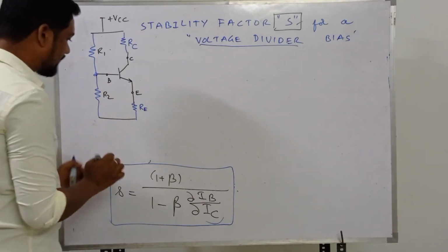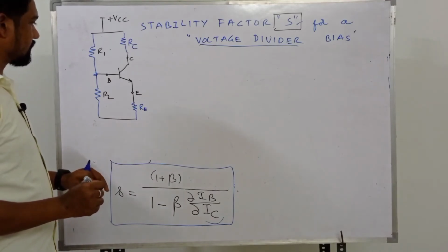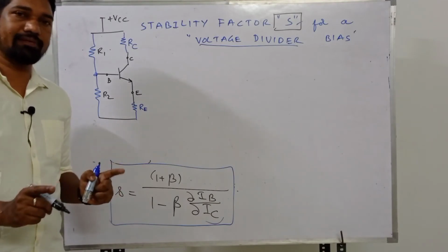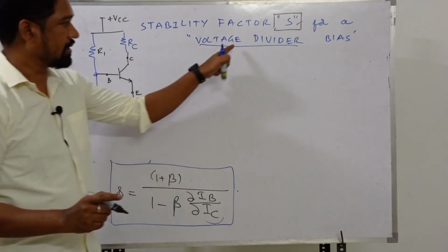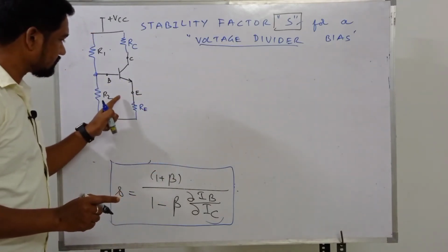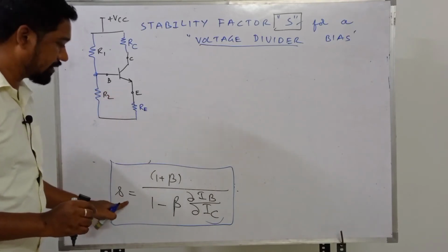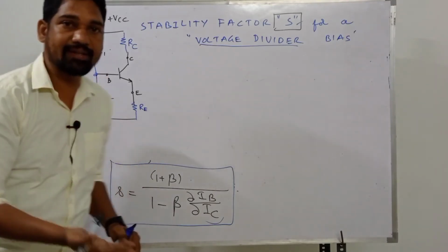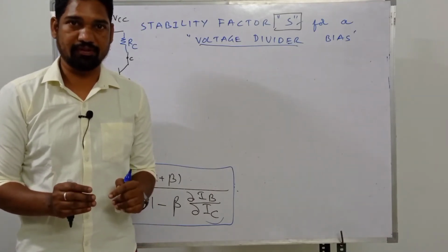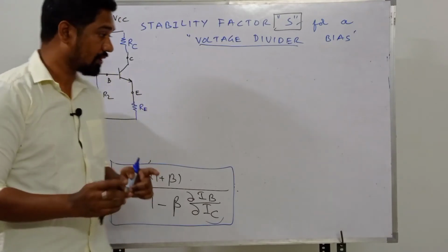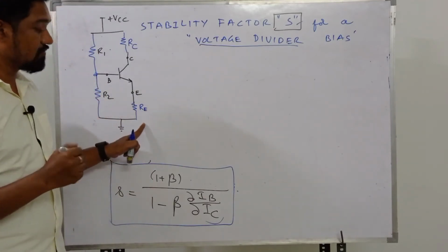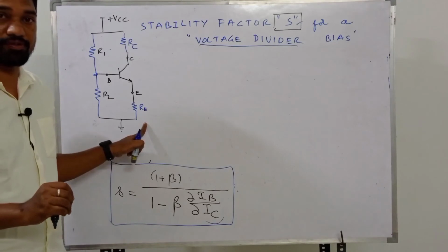So here guys, remember another important point to be noted down in capital letters. Yeah, you will have questions from voltage divider bias. We have another name for this one. You go in search of that one. While deriving the expression for the stability factor, or while designing a self bias, I repeat, while deriving the expression for the stability factor, or you will be given a numerical to design a self bias for meeting some specifications.